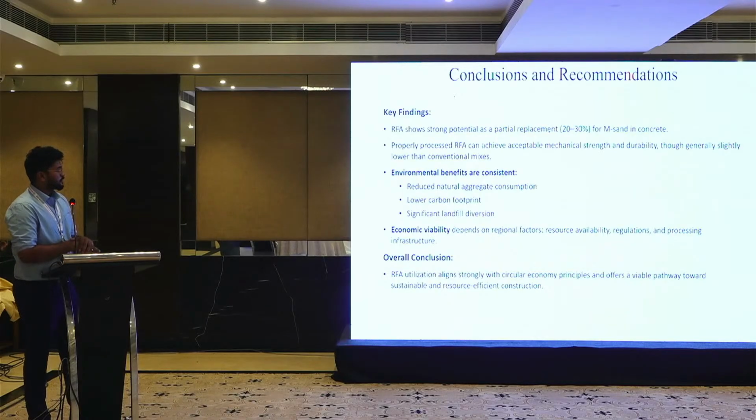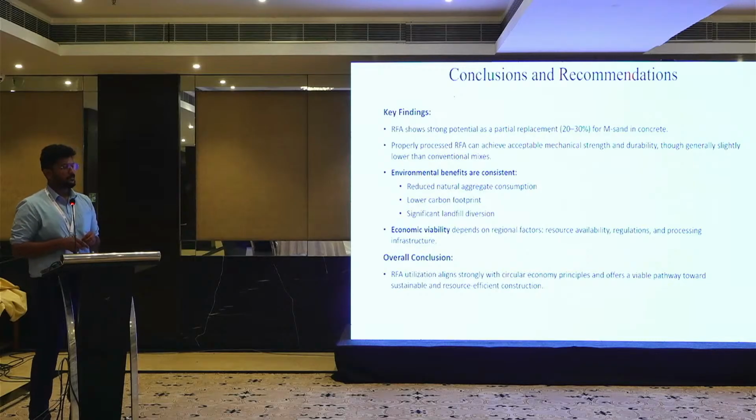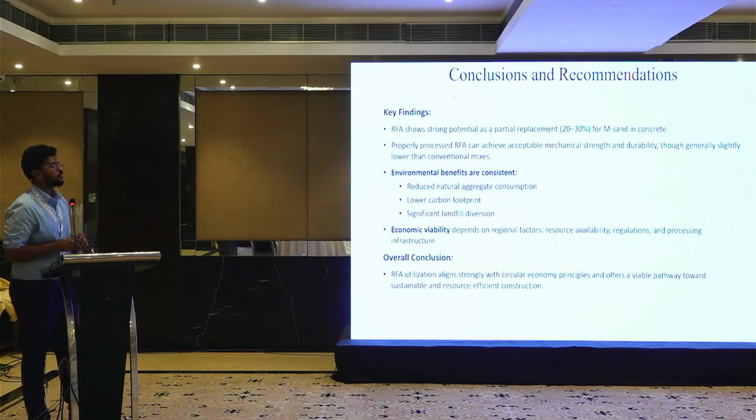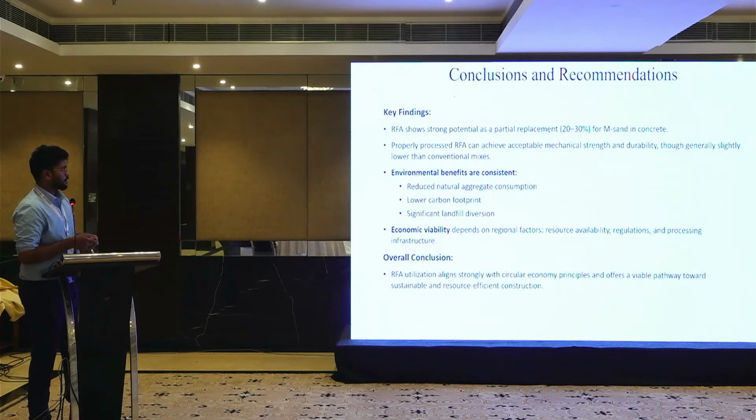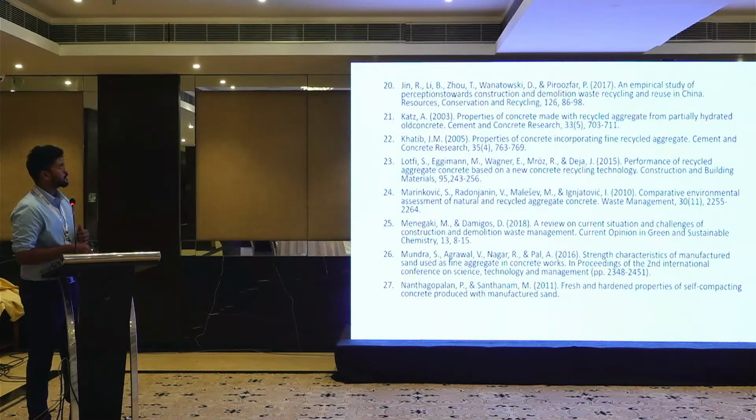So the key finding is that RFA shows a strong potential as a partial replacement of natural aggregate in concrete. It reduces the natural aggregate consumption, lowers the carbon footprint, and gives significant landfill diversion. So these are the references.